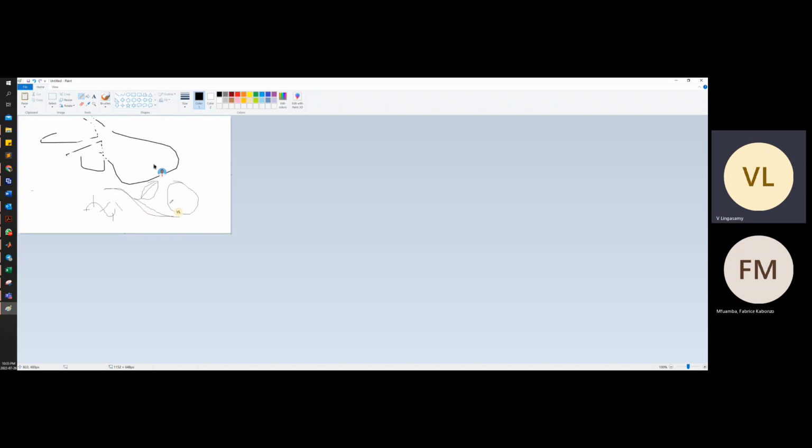Wrapping means I am wrapping between plus 180 and minus 180. Whatever value goes below this, it will be subtracted and then follow this curve. Whatever goes beyond this plus 180, if I subtract that, it will follow this one. It is kind of wrapping, following this sine kind of way. If I unwrap the phase, then it will be like this. That's the only thing.